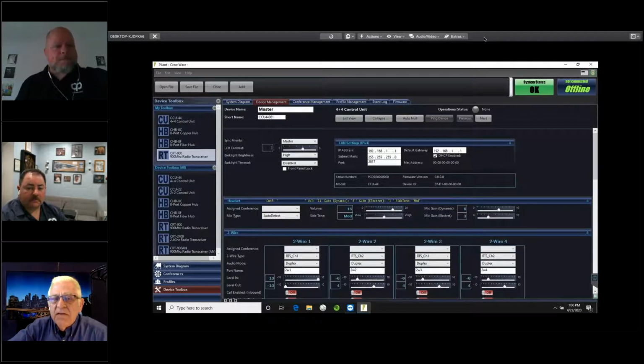Because aren't the channel numbers opposite? No. ClearCom channel 1 comes up as RTS channel 2, I believe. No. If you plug a standard ClearCom into an RTS channel, what you get is channel 2, because channel 2 is on pin 3. Channel 1 is on pin 1.